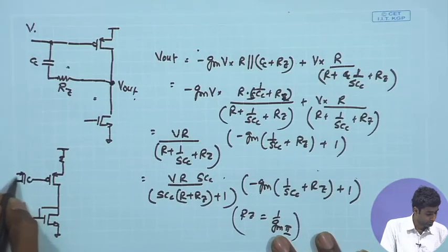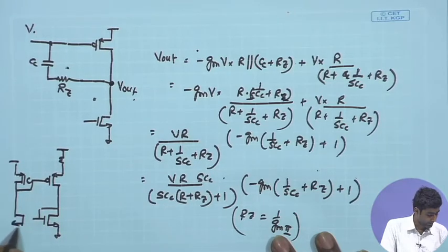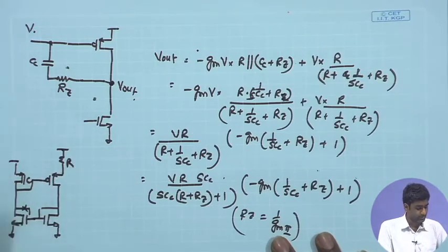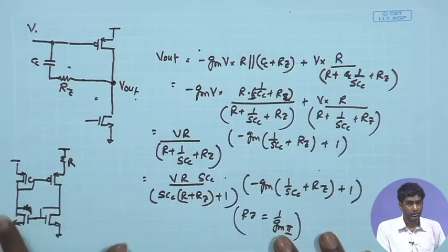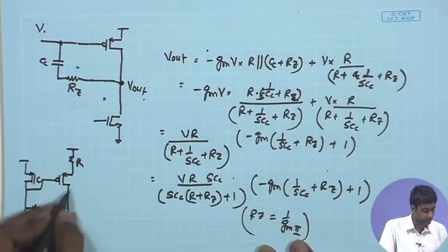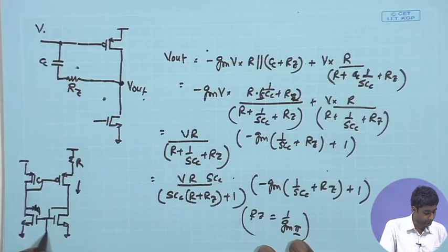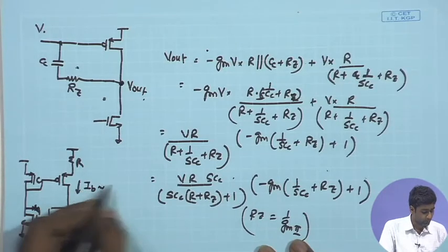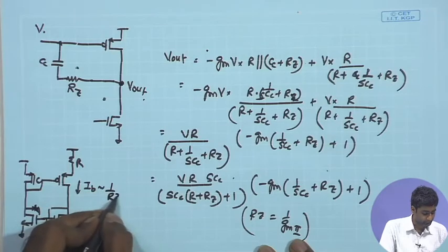We will be looking into this circuit in a little bit more detail, and in this particular circuit, if this is an R value which is being used, this is not a connection. So, if this is the R value, we can show that the biasing current that we get out of this I bias is proportional to 1 upon R square.